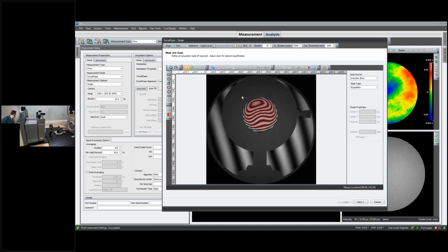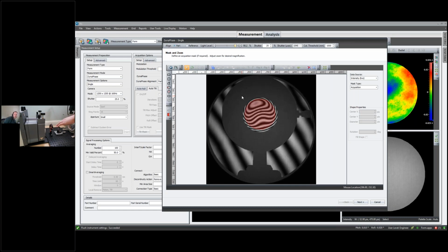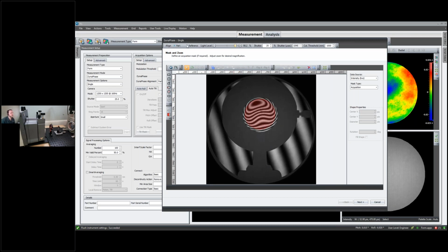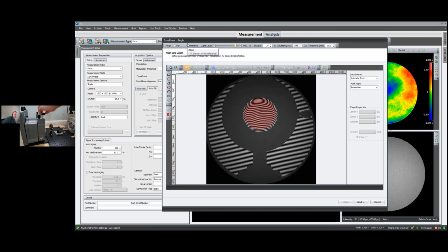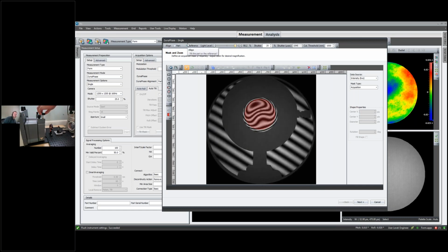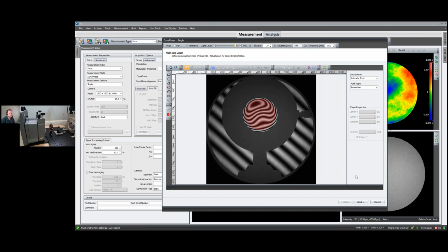In this case, I want to keep the optical axes of the beam reducer in line with the reference flat, or the return flat. So I'm going to tell the software up here that instead of tilting the test part, I'm going to use the tip tilt adjustment knobs on our accessory receptacle to induce the carrier fringe.